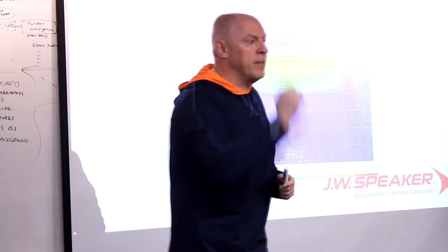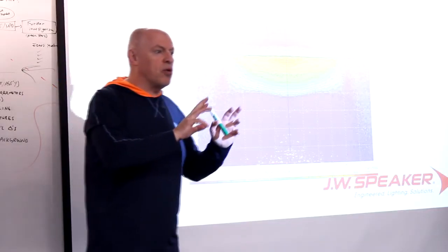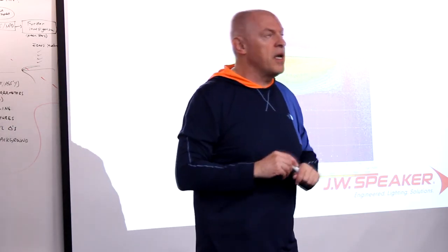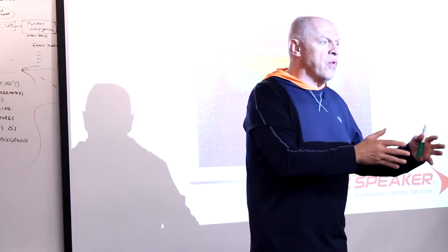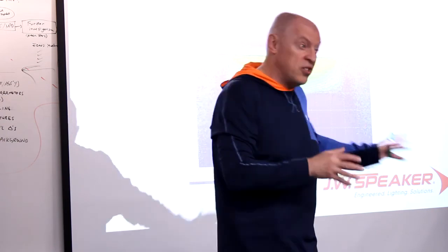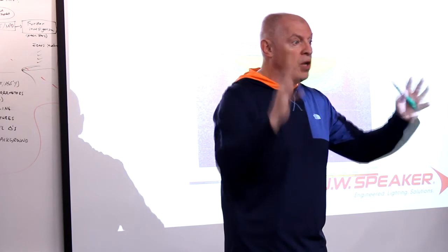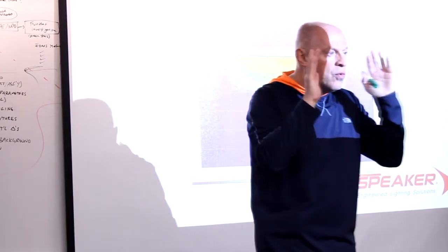Okay? Go ahead. I'm just wondering, is there a standardized window that we use and that competitors also use, or is it just whatever you decide? There is no standardized window per government or per regulation. Whatever we design, we at JW Speaker want to be really somewhat real and honest. So we pick this plus minus 60 degrees because we think in that window will be all kinds of light. When you are sitting in any kind of vehicle, your peripheral vision is 120 degrees.